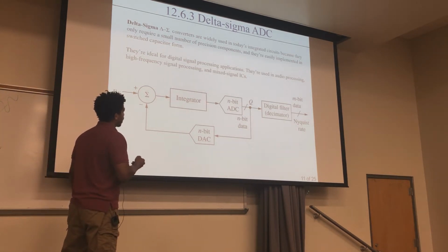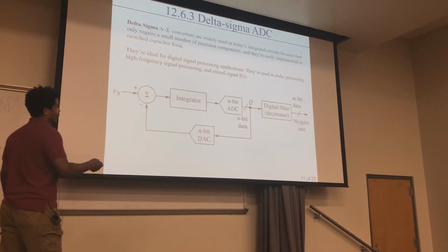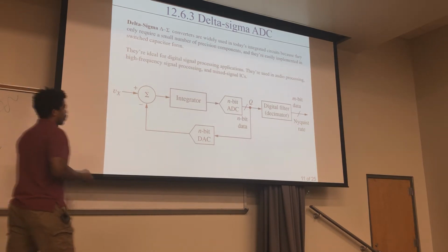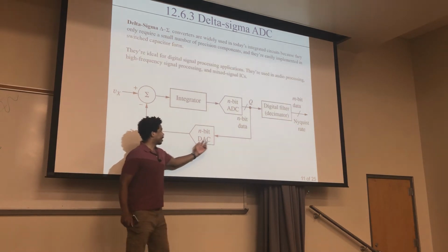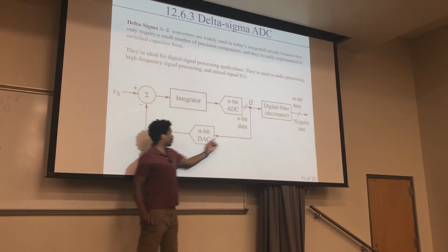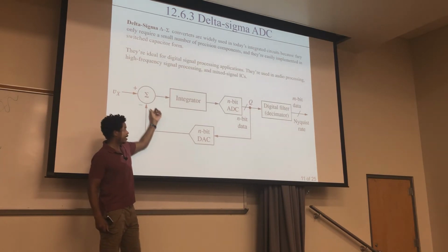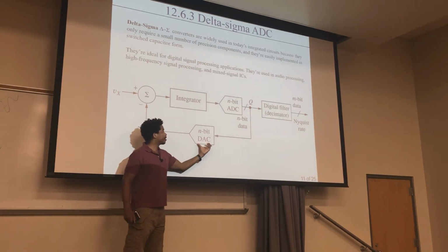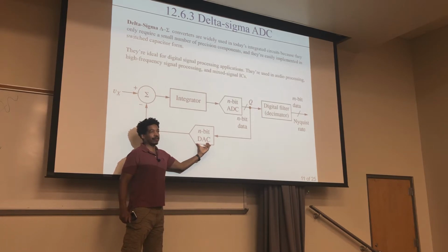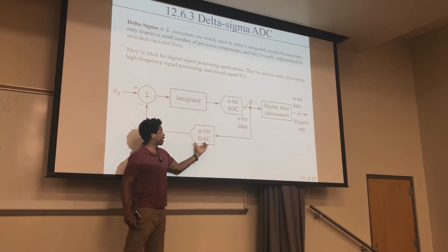And then what comes out of here, you take from analog to the digital domain, and you feed that out, right? But you also take off that signal and feed it back. So this piece is in the digital domain, so you go from the digital back to the analog to mix it into the signal. This piece is doing a correction of what has been integrated there.